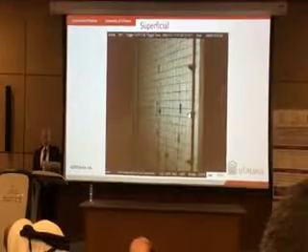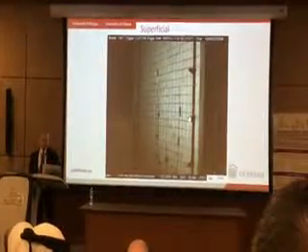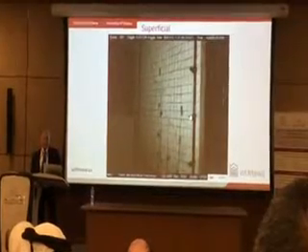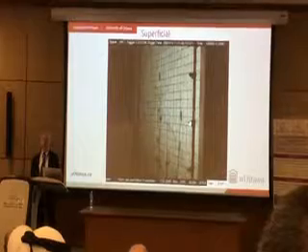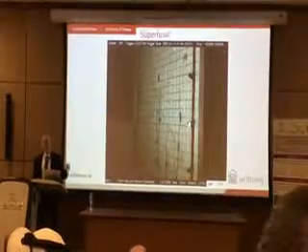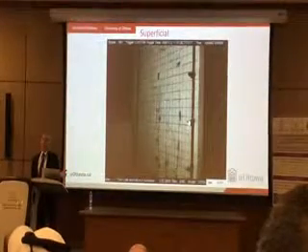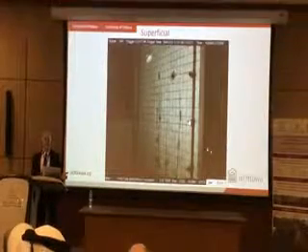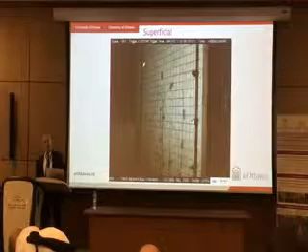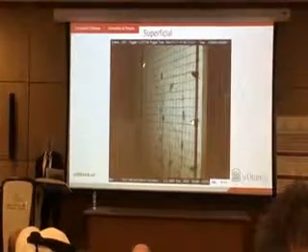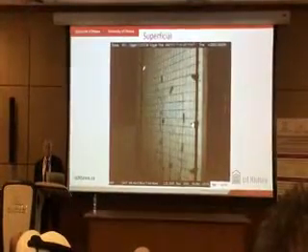Now, here is a slab of a parking garage that we tested. As you can see, this is the second shot, and we marked the cracks. It deflected, it bounced back. There's no permanent deformation, which means there's no yielding. This is okay. You can continue using the building. It could either be immediate occupancy or even operational, because the damage is superficial.